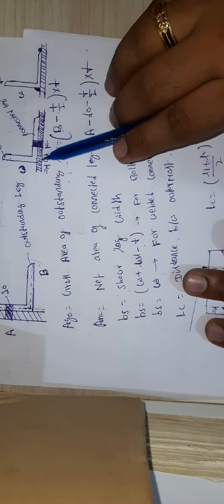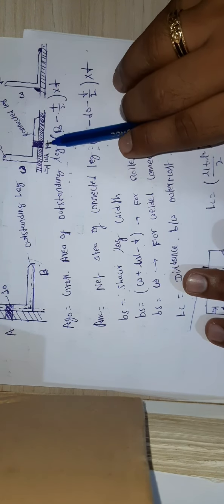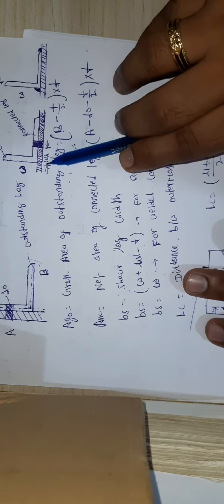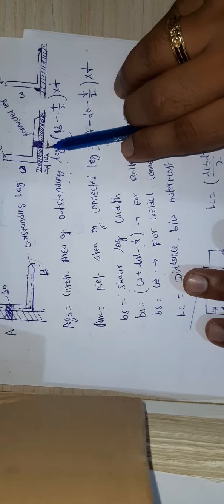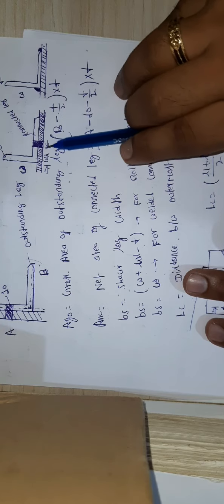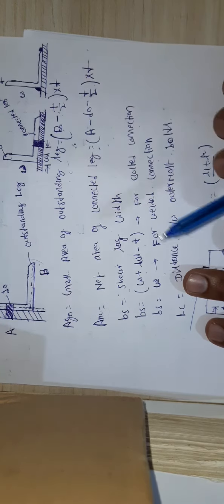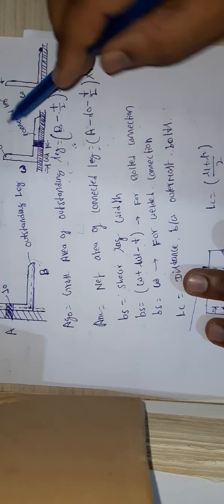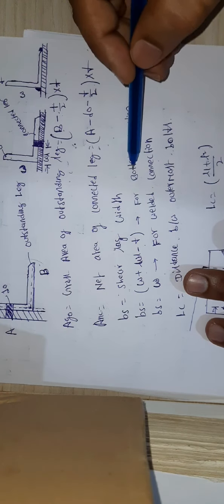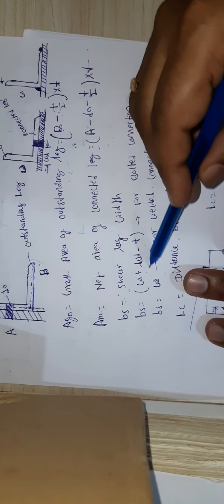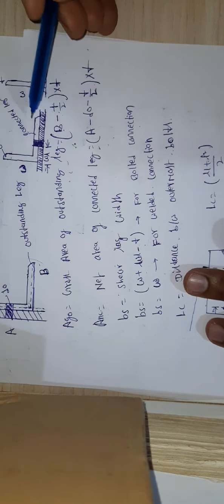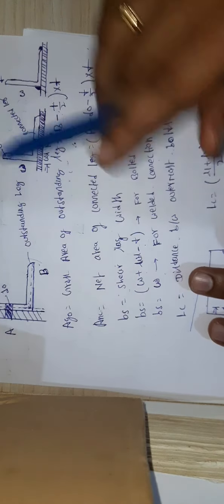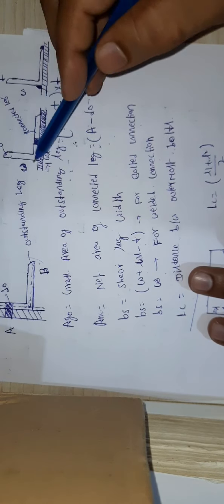W_L is the distance from the bottom of this connected leg to where you connected the first bolt, so that is length W_L. And T is the thickness. So this is for bolted connections. For bolted connections we need to use this formula. It is there in the IS code, guys. Please refer. I am just explaining the terminologies that you will use.